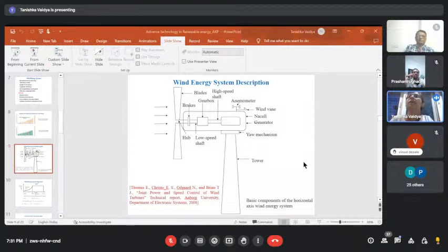That is to avoid the failures of the mechanism: proper lubrication system, then the temperature of that lubrication system, viscosity, to maintain the temperature and even viscosity of the lubrication system, and a few more things which are there for the automation, that we'll see in the next slide.